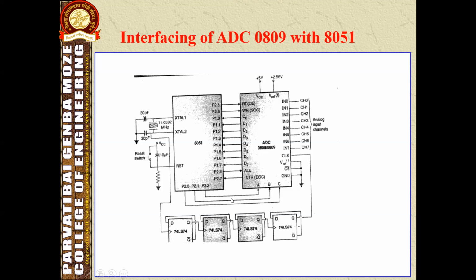Then we have to wait 50 nanoseconds for the address to be latched, and it can be obtained by sending the ALE signal. So after connecting, we have to wait for 50 nanoseconds. Then the address will be latched by activating the ALE pin. After activating the ALE pin, only then will the address be accessed.